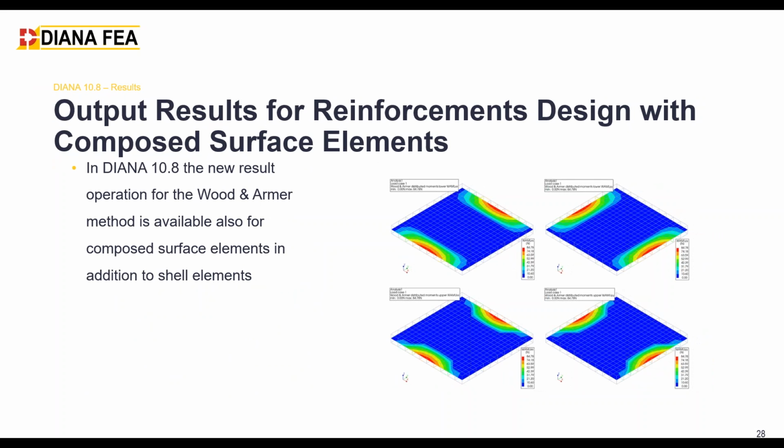This new result operation for Wood Armer method is also available for composed surface element in combination to the shell element. So you can, in a similar manner, that what is computed for shell element, you can also ask for this result for composed surface element. So it will give you some distributed moment and distributed forces based on this combination.